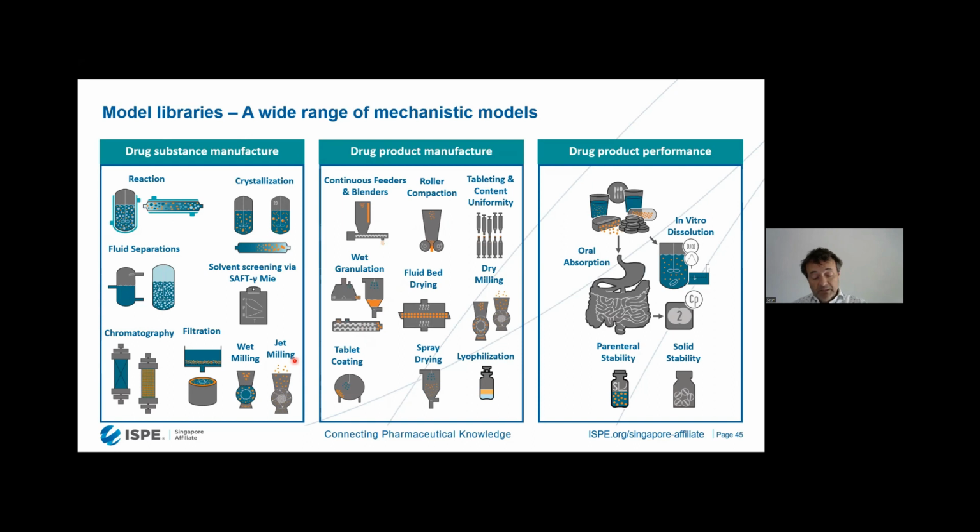In some ways, tableting is a continuous process, but most of the other steps will typically be batch. So we can model batch, for instance, high shear wet granulation and a batch fluid bed drying before doing tableting, which you could consider continuous, and then a batch tablet coating operation. If you have particular applications in mind, I'd be more than happy to answer an email or get on a call.